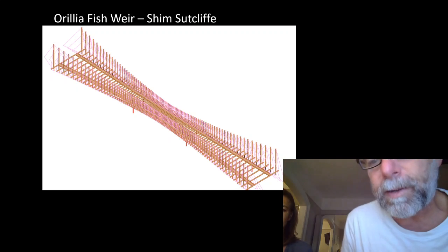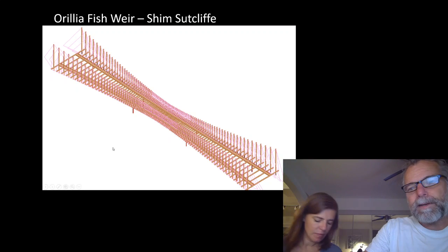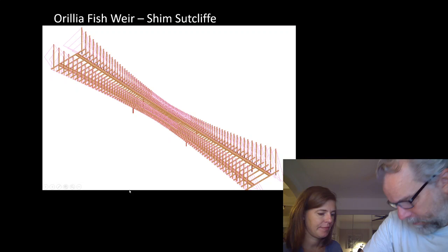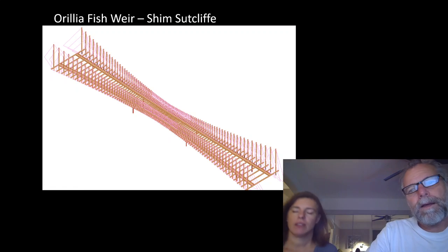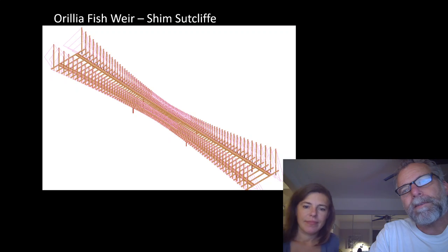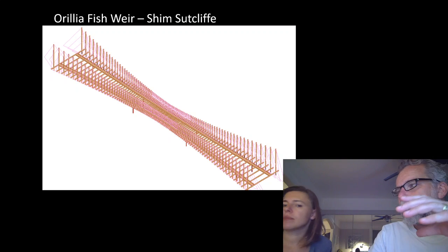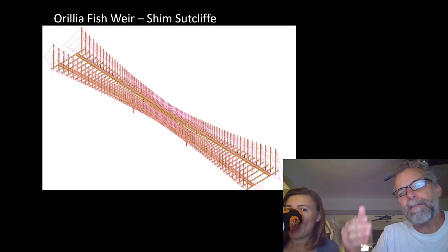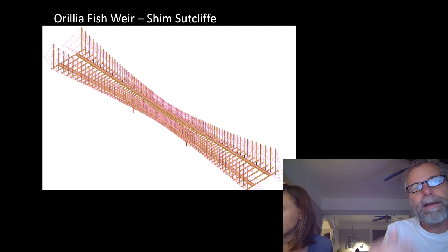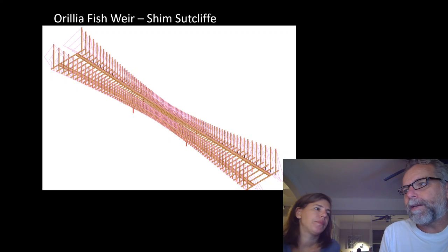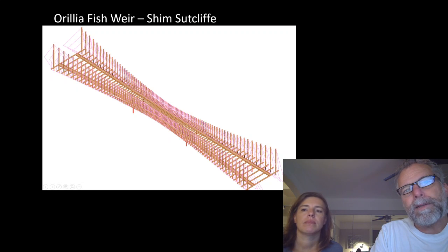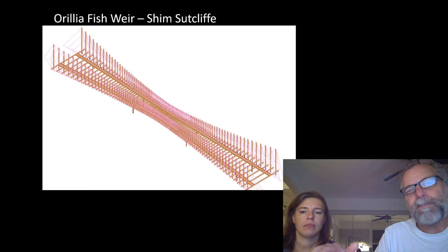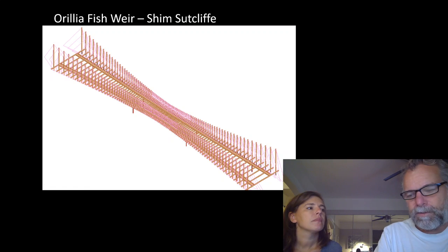This truss is going to be stick built, which means it's not prefabricated as a truss. It's brought in one piece at a time, in which case we need a platform to build on. So the bottom chord of the truss would have allowed them to build almost like a staging platform, and the balance of the truss erected.